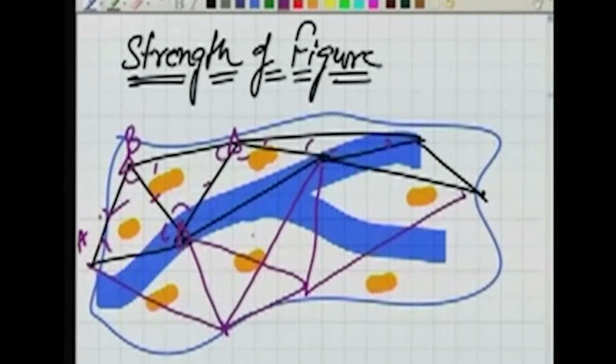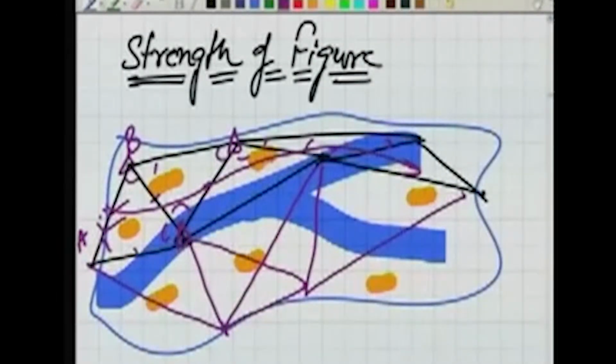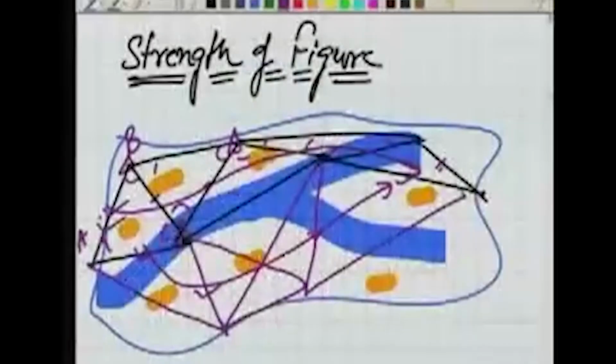So we are doing one job by two sets of triangulation systems, or two sets of triangulation figures. So this is one route by which I can establish the control, and the second route which is possible here is, I start from this known length, then I compute this, and then in this quadrilateral I compute this, then finally this again. So I have got a second route. So to do one job, computation of this length, I can do it from two different triangulation networks, two different figures.